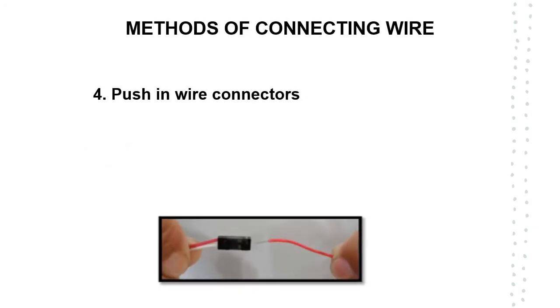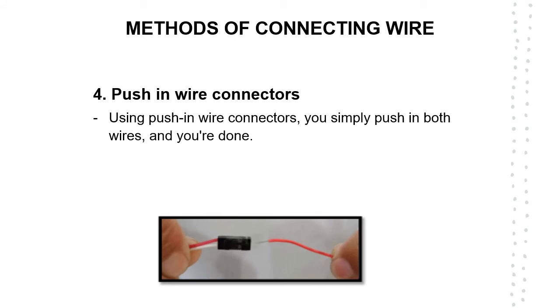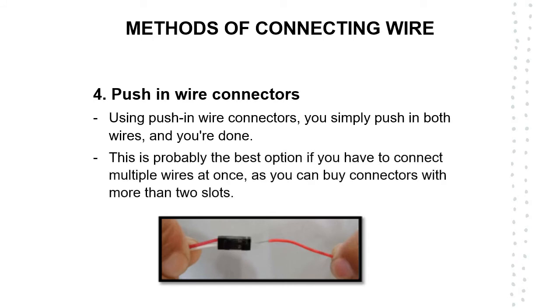Number 4, push-in wire connectors. Using push-in wire connectors, you simply push in both wires and you're done. This is probably the best option if you have to connect multiple wires at once, as you can buy connectors with more than 2 slots, like this one.